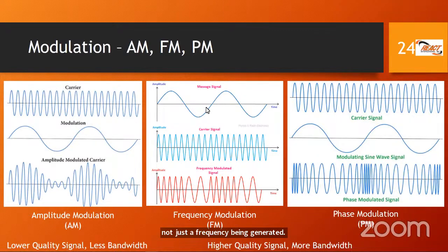Then we throw our voice. This is our voice here, our message. We speak, and then we throw that onto the carrier wave. But we modulate it frequency-wise. So we don't amplitude modulate it, we frequency modulate it. And that means we shift, we increase and decrease the frequency, and we end up with this.